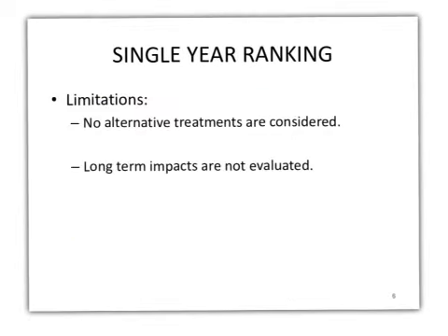Some of the limitations that we may face by utilizing the single year ranking: the very first one is that no alternative treatments are considered. Typically we would pick one treatment that has the least cost and go with it. The other limitation is that the long-term impacts are not really evaluated. We don't see the overall length or longevity of the applied treatment. It would be mainly related to the ranking criteria that we pick and the associated cost.